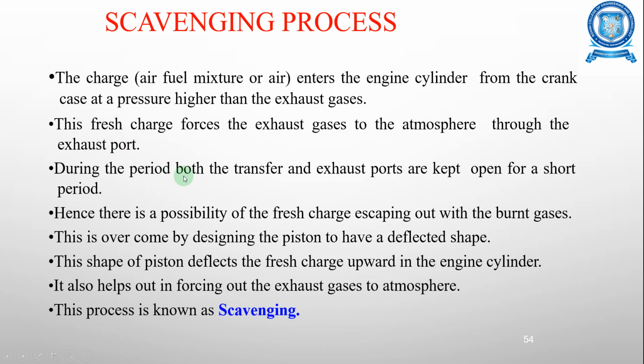During this period, both the transfer and exhaust ports are kept open for a short period, and there is a possibility of the fresh charge escaping out with the burnt gases. This has to be overcome, so the piston crown has been designed to have a deflected shape.